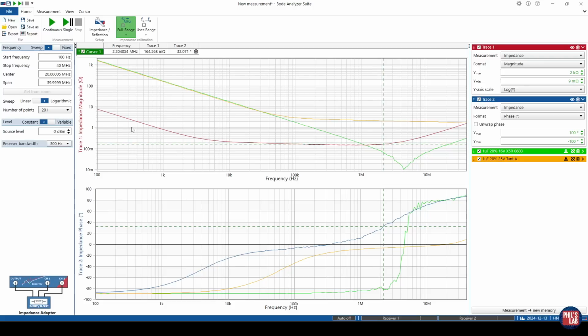those low frequencies. Because this is an aluminium electrolytic, we also will have a very flat ESR profile before the ESL kicks in. So from about 10 or 20 kilohertz, we've already reached the lowest impedance we'll reach for this particular capacitor. So if I'll move my cursor over this, at 100 kilohertz, our impedance is about 170 milliohms, which is significantly lower still than the tantalum capacitor in this particular case. So it might, in certain cases, be more usable than the tantalum, although it is much larger, much bulkier, has far greater capacitance.